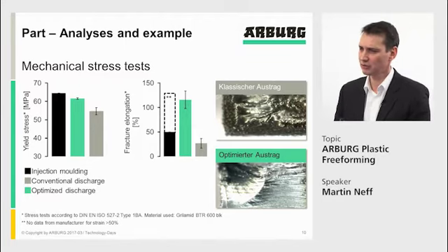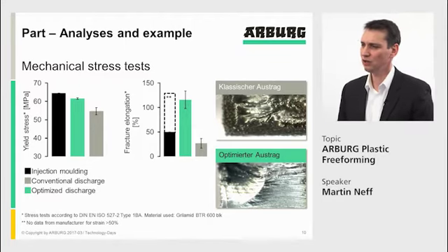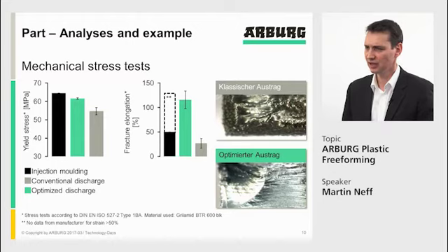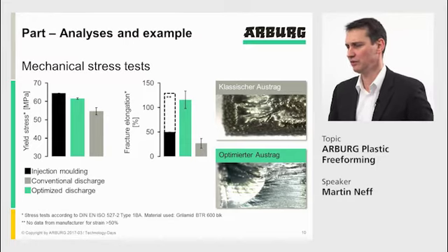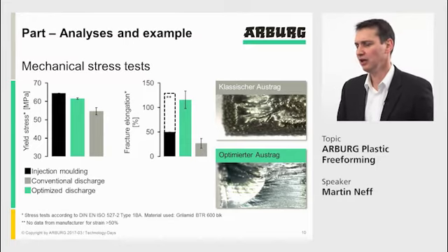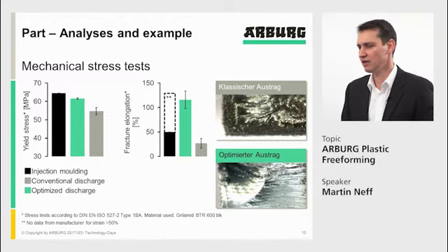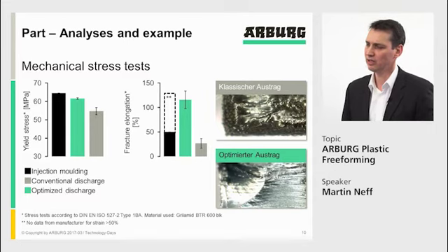Respectively, the part breaks earlier. If we look at the optimized discharge in the lower picture, we see that the borderline is really melted nicely together. You don't see any droplets, and you see a really nice breaking of that tensile bar.